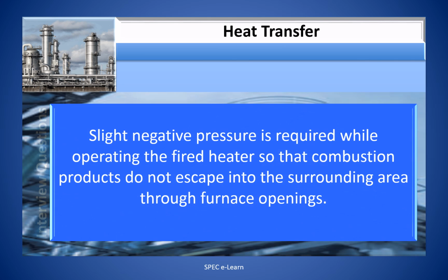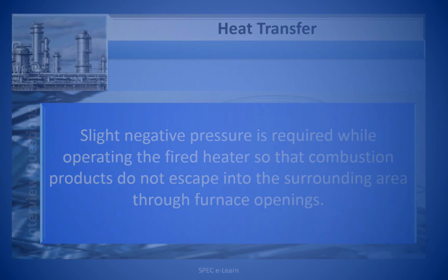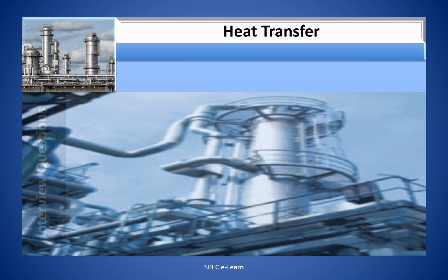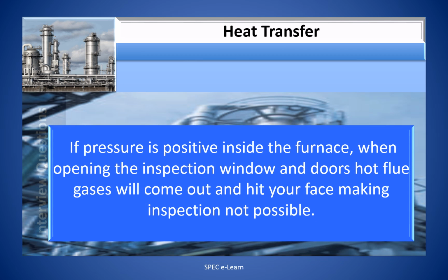Slight negative pressure is required while operating the fired heater so that combustion products do not escape into the surrounding area through the furnace openings. If pressure is positive inside the furnace, when opening the inspection window and the doors, hot flue gases will come out and hit your face, making inspection not possible.